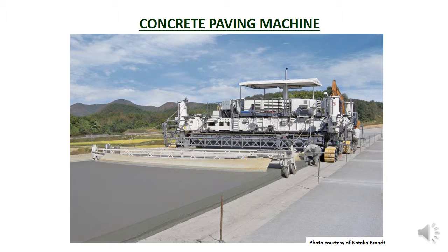This photo shows a concrete paving machine that automates the laying of a concrete road. The paver has its own engine which powers the tracks and the concrete laying machinery, so once set up, the paver just trundles along on its tracks laying the road. The paver has laid the material in the foreground and is moving away from the camera. Note the concrete is a special dense mix which stands up on its own, so formwork is not required.